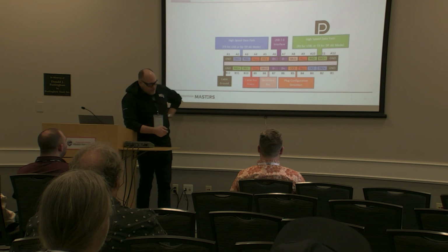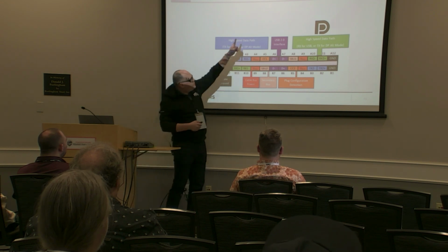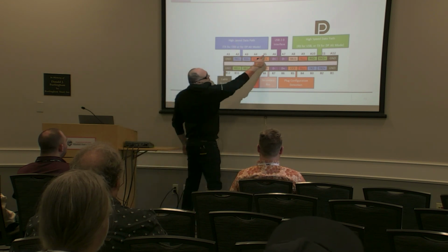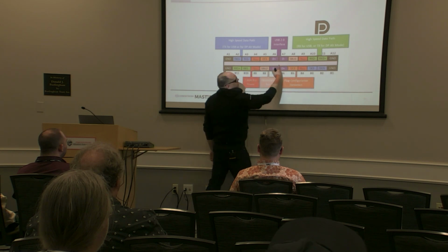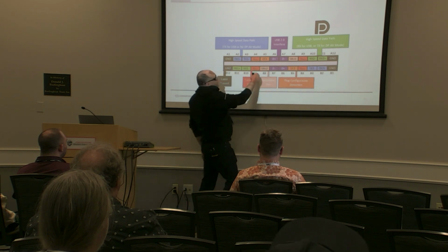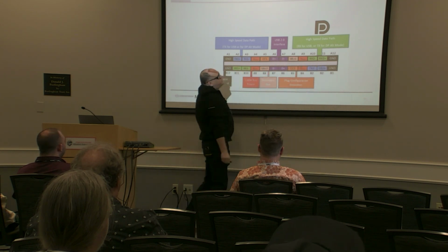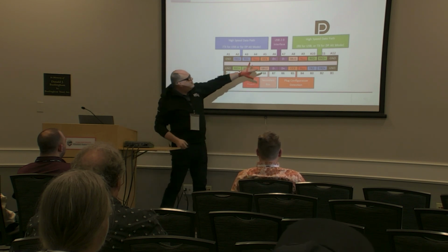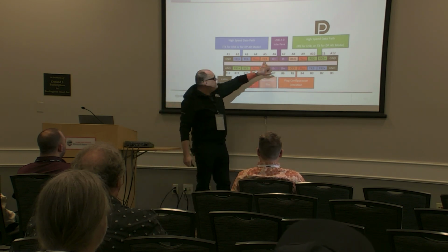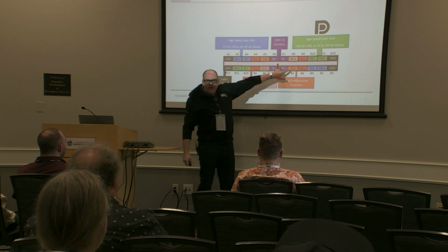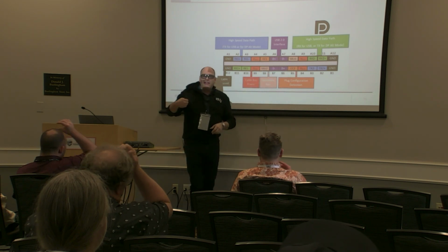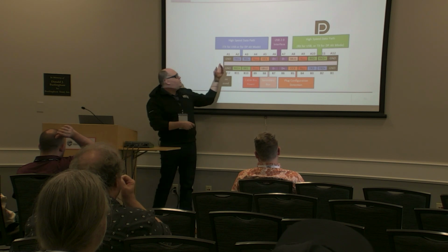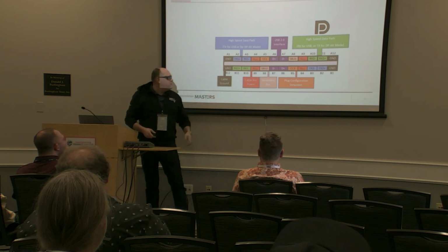Yeah, because if you put it in this way, with the top up like this, you're using these channels and these channels, right? But then when you flip it, you're using these channels and these channels. So you've essentially just reversed it. That's how it's able to work. But the way it does that is it actually has this CC1 and CC2 pin. That's how it identifies the directionality of the cable. And then it says, okay, well, this is going to be my A1 and this one's going to be my B1, right?